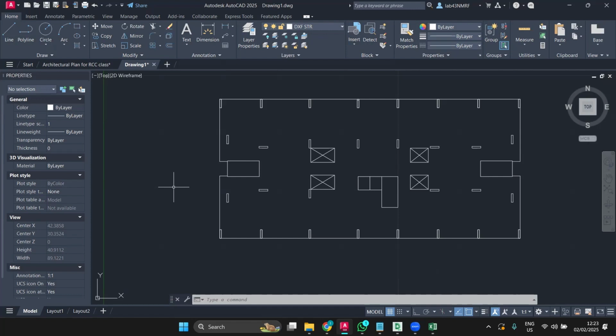Then what you will do is try to increase the wall thickness and increase the columns unnecessarily, because of a lack of concept. You understand what I'm trying to say? You're 100% right, the shorter direction is the weaker axis, so you need to place your columns there. But at the same time, you need to give a little importance to the longer direction as well. If you don't place any column in the longer direction, where will you get the stiffness?